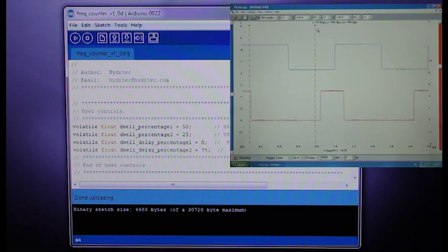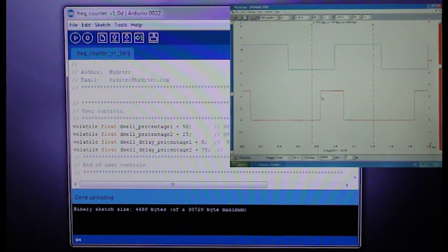Okay, once more we see that if we place the X cursor at about 750, the leading edge on the output should be starting around here, but we have this latency. Let's measure the latency. The latency appears to be about 93 microseconds.